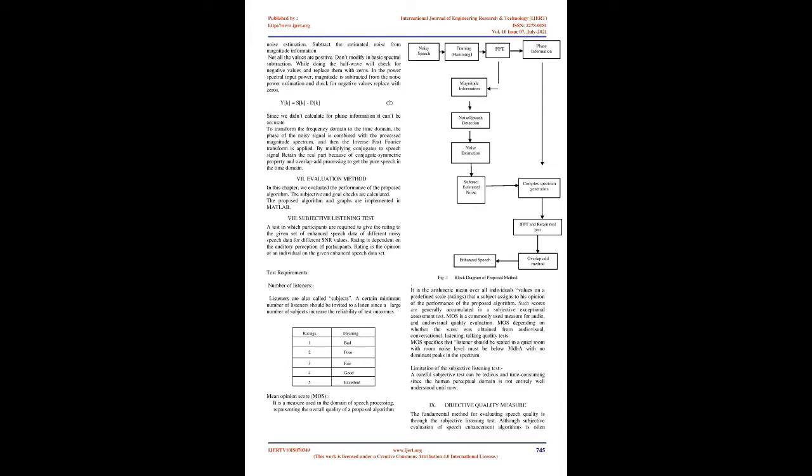The processing of the FFT signal should be finite, so the continuous time domain signal is divided into overlapping chunks referred to as frames. To preserve the continuity of the signal, 50% overlapped FFT is applied to every frame. 5. Estimation of noise spectrum. Noise estimation cannot be calculated previously; it can be estimated at the beginning of speech, when the speaker's lips are closed. For around 2 seconds this can be used for estimating the noise. The average of the first 5 frames will be the noise estimation Dk. We calculate the average noise estimation.